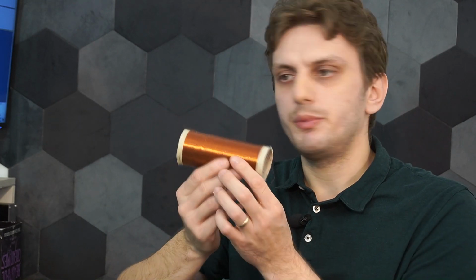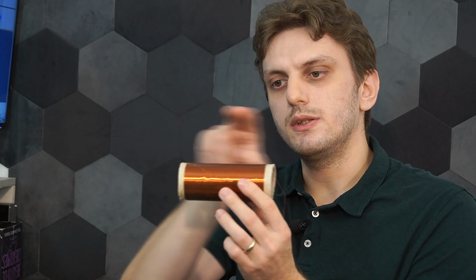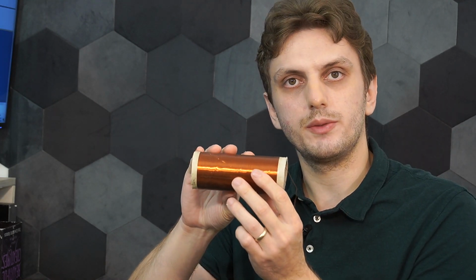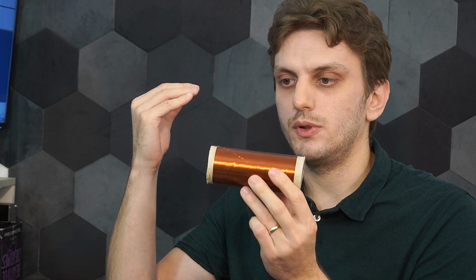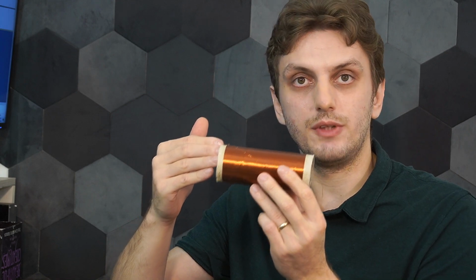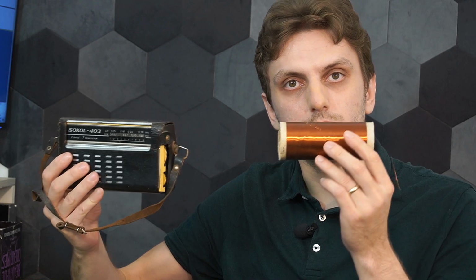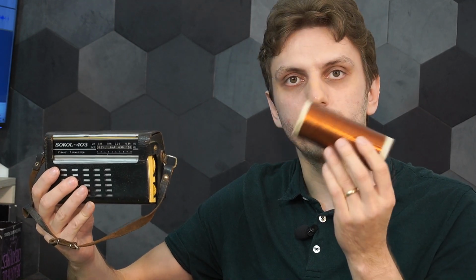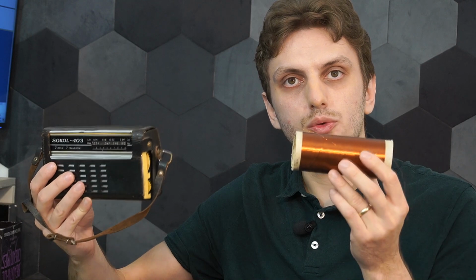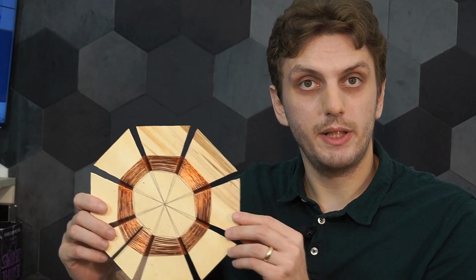For the solenoid shape, you have a very directional field that comes back close to the inductor, and although this should be able to achieve the highest distance, if the inductor and the radio are not perfectly aligned, so if there's any sort of misalignment, then the two will couple very poorly. On the other hand, with the spiderweb shape, the field is far more spread out, so you don't have a very linear field, but rather it spreads out all over the place.